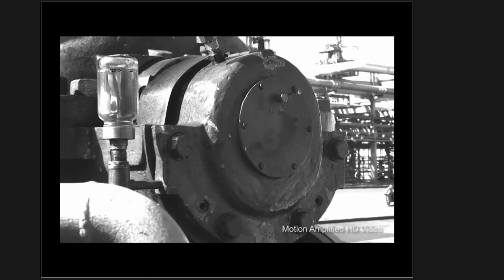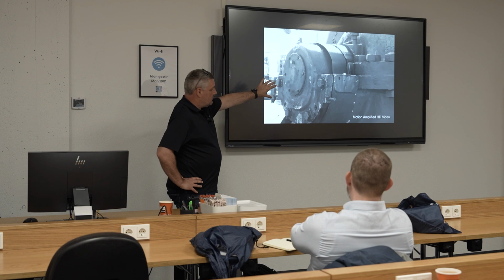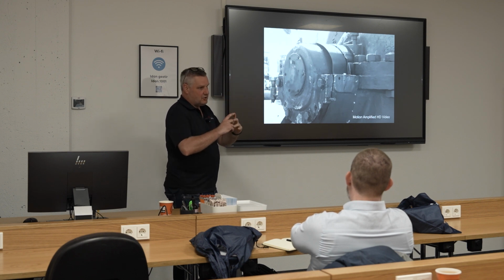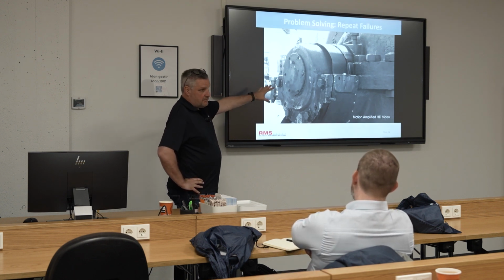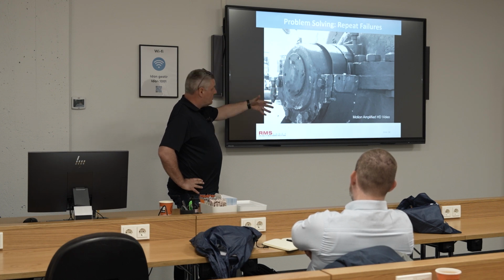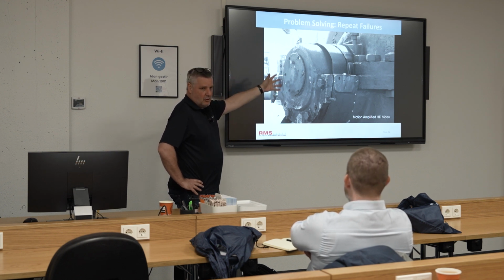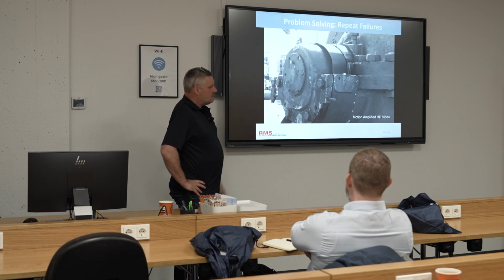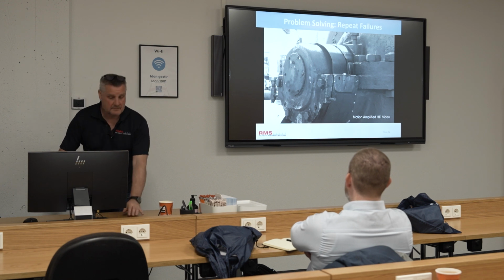So what they found within that bearing, they machined the bearing housing, it was oval. So the bearing, I don't mean like an egg, but it wasn't concentric to the bearing journal. So the issues with the bearing, the pump manufacturer machined that, sent it back like that, and then they got the information. This is why we do before and after, that we can look at it. It wasn't like that when it went away. So it's been repaired internally, had a new impeller, new bearings, and look at it now. It's nice information to have, really.